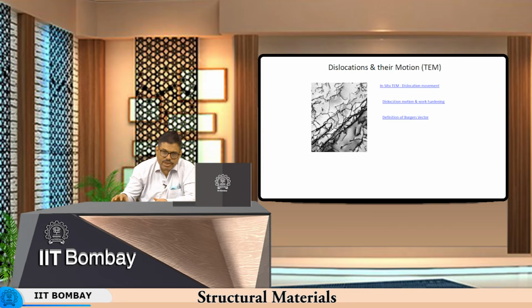So these dislocations therefore manifest on a macroscopic scale in the form of work hardening. So material behaves harder as the dislocations multiply and interact with each other, stopping each other's movement. I told you that for material to deform permanently, dislocations have to move, right?